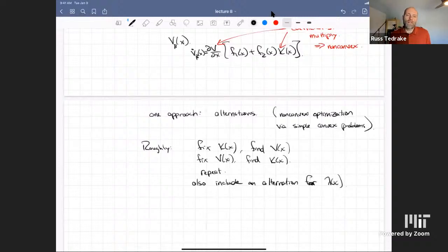So these are low dimensional, which we do mostly to think about it. But the place we pushed this the most a few years ago was for quadrotors flying fast, and airplanes flying fast around obstacles and things like this. That's a pretty complicated system. We got tens of state variables and very non-trivial dynamics, including actuator delays and everything to get it really working, and obstacles that were moving at runtime.